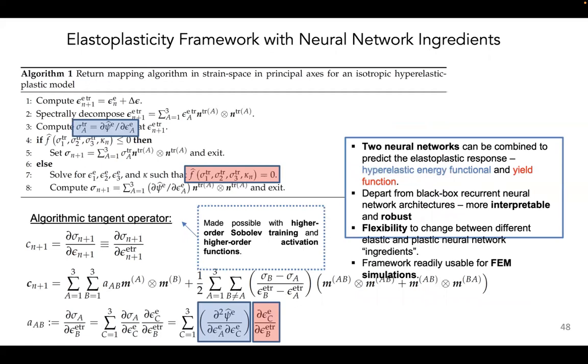So in terms of implementation, like what we talked about, the price you need to pay is that you need to know how to write a plasticity model. But if you already have the plasticity model, the benefit you get is that you only need to make a change in the part that I put in the bracket. If you have a return mapping algorithm, you only need to make a few changes, and then you can obtain the change. It's actually a minimum surgery.